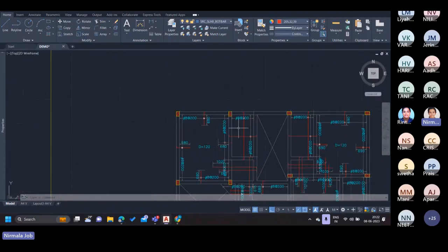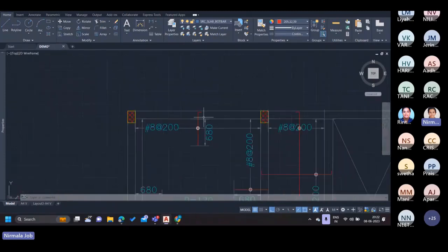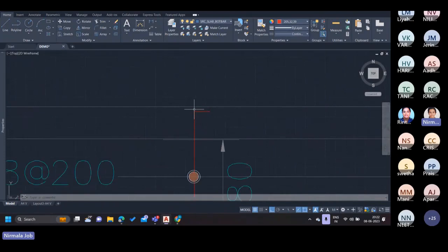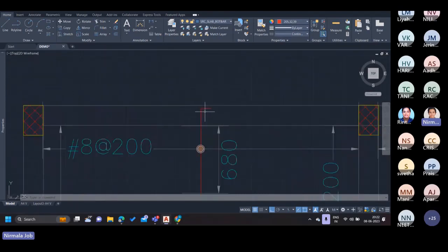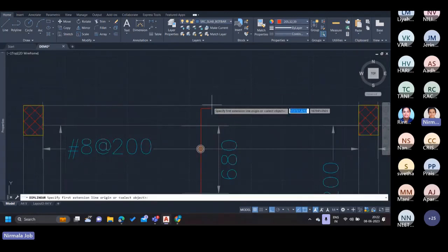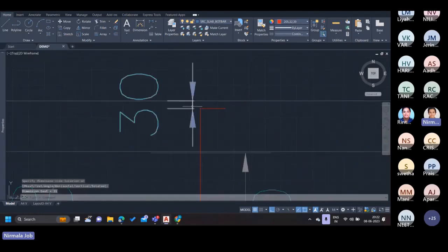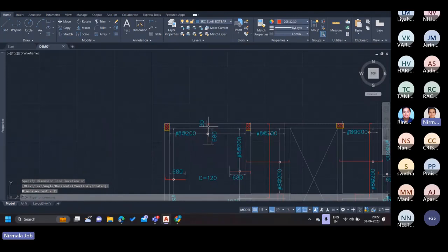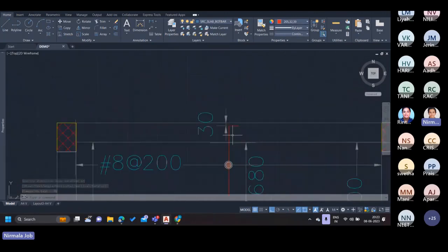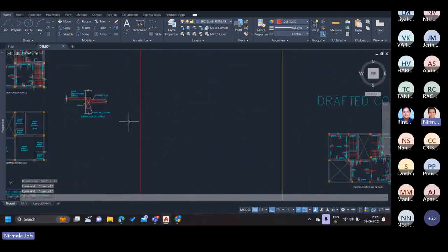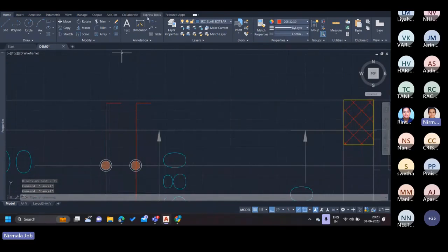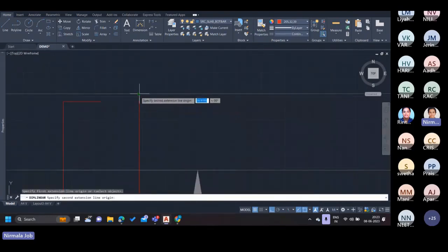And the next check is to ensure that the rebars are placed with proper cover. As we know, the member along which my cursor moves right now is actually a beam, and the cover provided for a beam is basically 30 mm. And we can see in this figure, that is the drafted copy which I have edited, I have changed each and every cover into 30 as per the requirement. But in the structural drawing which we will receive, the cover might not be actually 30.